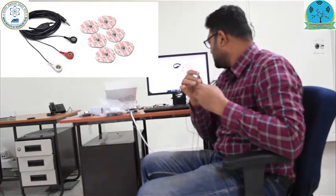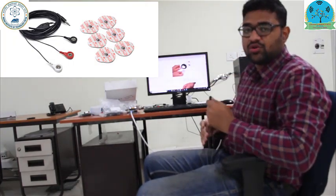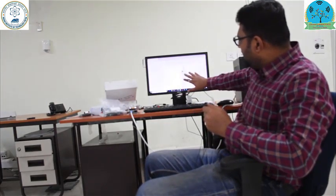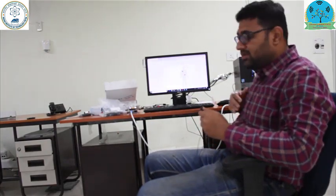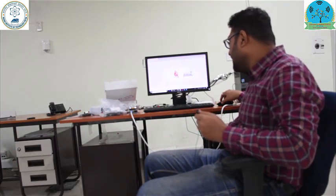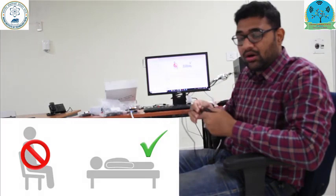As discussed before, we will deploy these sensors on the chest as shown here, and we will use surface electrode gel, which I showed before with the MySignal Kit, and we will deploy it on the human body like this. So the positive goes here, negative on the left hand side, and the neutral on the right hand side. To monitor the right ECG, somebody should be lying down rather than standing or sitting.